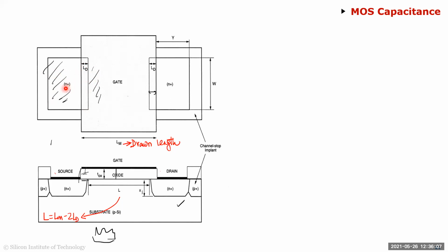In both cases, the dopants diffuse into the substrate. But when they go downwards, they also go sidewards. Because of that, the source and drain extend a little bit into the gate area, which is actually fine. The other way is not fine. If you have a gap, then the device is going to be completely off. If you have an extension inside, that's fine.